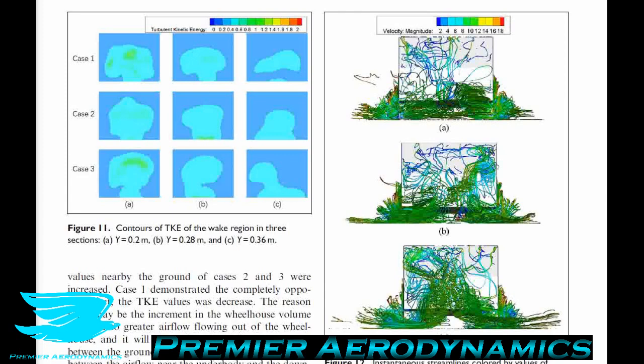One major benefit of instantaneous streamlines is that they can show transient flow features, which time average streamlines can't do, because time average streamlines average everything out. So a flow feature that might only be present for a few tenths of a second each second might get averaged out by time average streamlines, but for instantaneous streamlines, you can see it. Anyway, let's discuss what we can see in figure 12, and we need to take it with a grain of salt, because they are instantaneous.